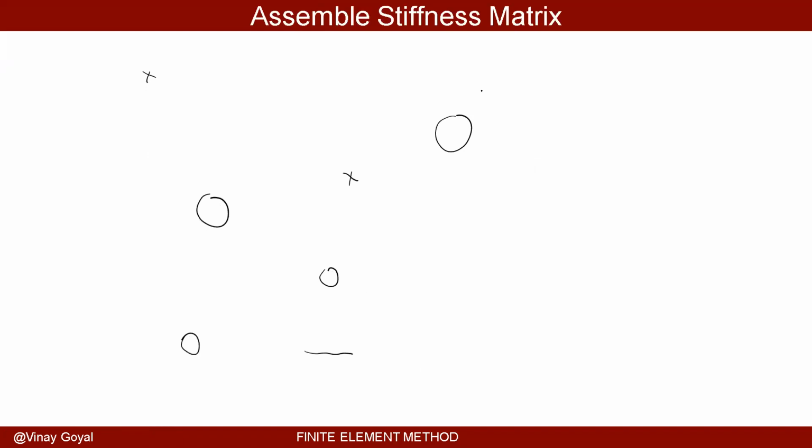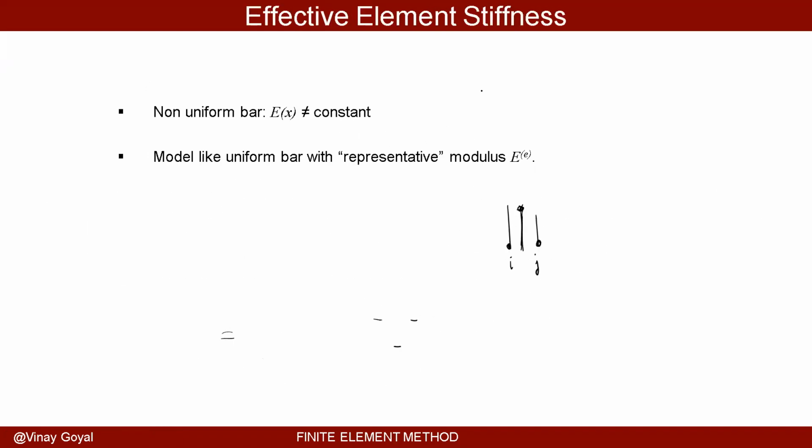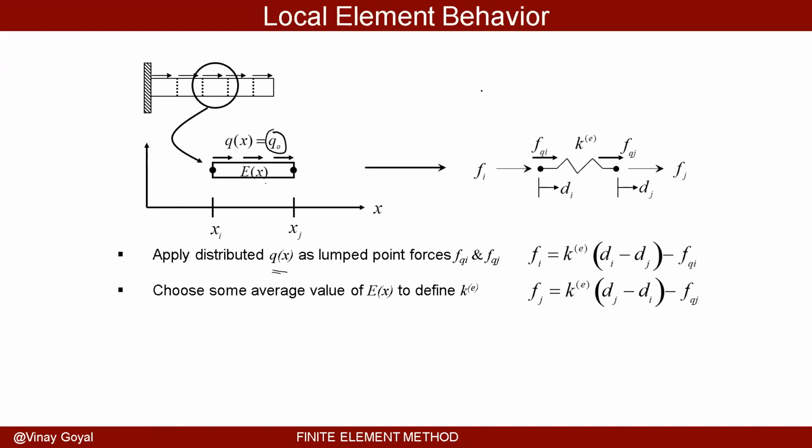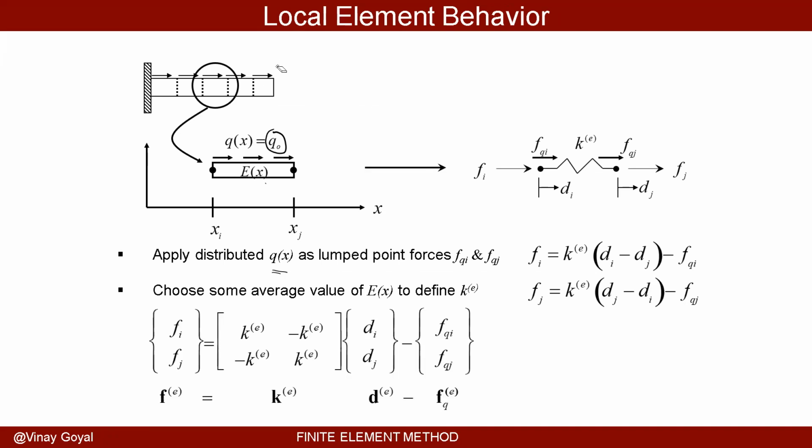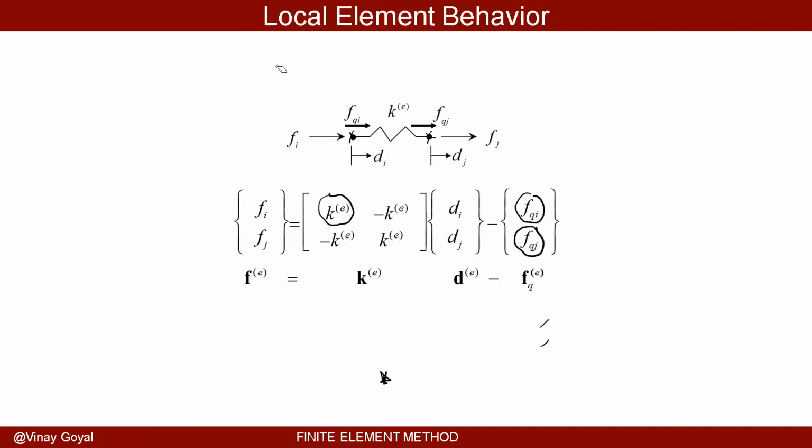If you look here in the example that we have, let me go back to the example. All we have is this distributed load. That's it. We don't have a point load anywhere. No concentrated load. It's all distributed. So for that reason, the concentrated force vector is going to be 0 in our example.